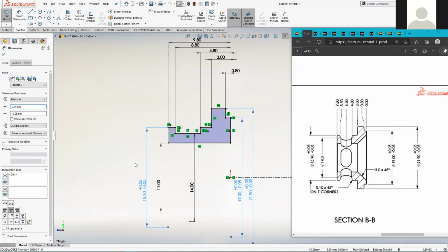It's a nice little introduction to show you that it is possible to store them within the part itself. Because the other option for producing a drawing like this is to just manually add these in at the drawing stage. But that's by far the least preferable way of doing it. By far the best way of keeping track of them is to bake them into the part itself, so that then any changes that you want to make, you just refer back to the part itself rather than adding them in willy-nilly as you create the drawings.